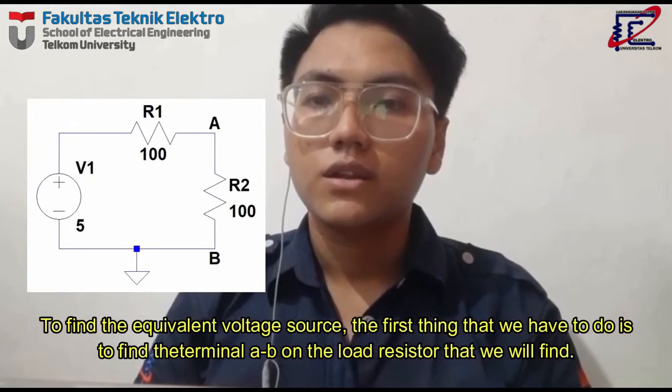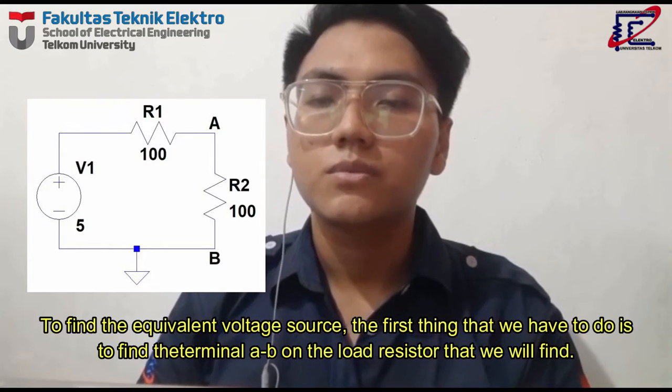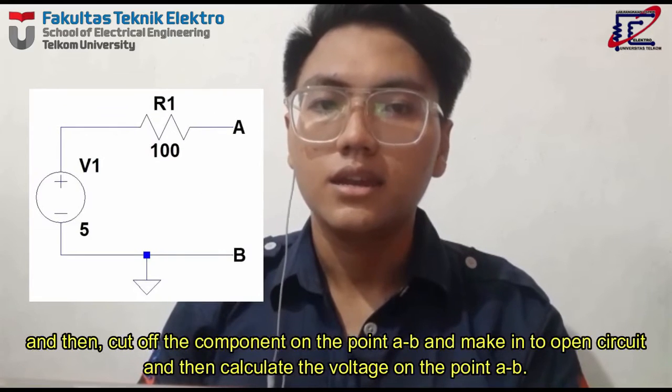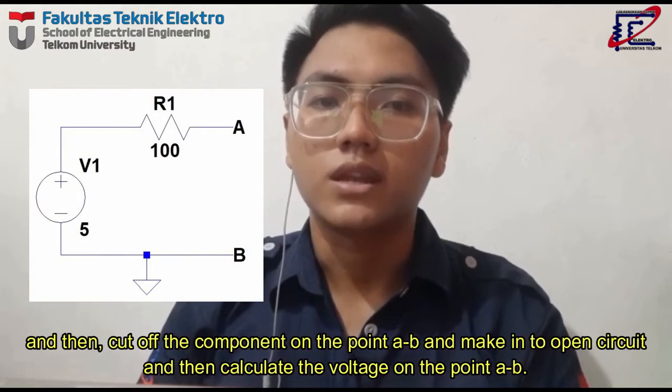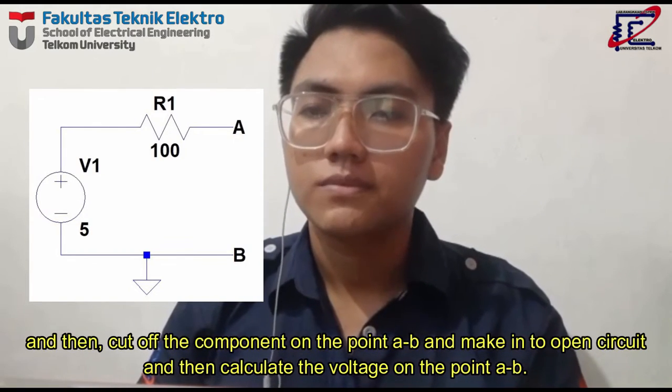To find the equivalent voltage source, the first thing that we have to do is to find the terminal AB on the load resistor that we will find, and then cut off the component on the point AB and make it into an open circuit, and then calculate the voltage on the point AB.